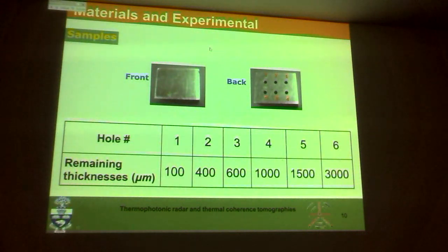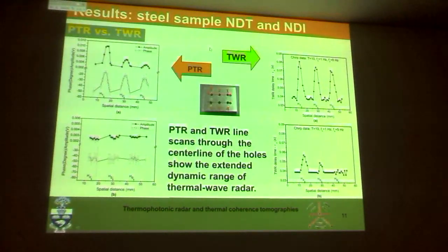With tissue it is different because light propagates in the tissue, so I can do better with tissue. But this one here is the most stringent kind of measurement, which allows you to see how good your methodologies are. So let's say you stick to a photothermal measurement using photothermal radiometry that I showed before, which is a single frequency at a time, and you have a pretty good idea what frequencies you want to use, because the frequency has to be low enough to be able to reach the defect below.